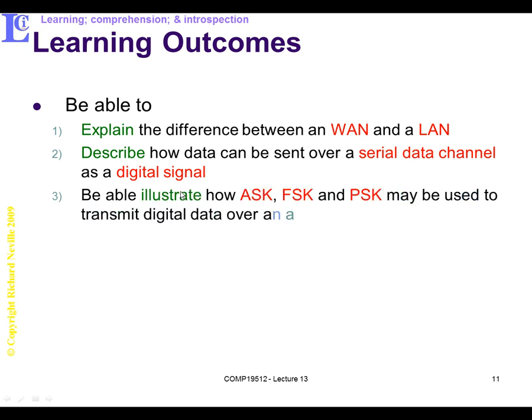Then we move on to talk about the fact that in reality we cannot send a digital signal across free space. That means wireless transmission and Wi-Fi is not digital. You might have thought it is. The main reason for this, a bit beyond the scope of the course, is that if you ever worked out how to transmit a digital signal, you should go down to the patent office and patent it, because it's nearly impossible. Think about how you transmit that transition from a 0 to 1, and how you'd make that change from low to high very quickly. It actually requires a very, very wide bandwidth, so it's not done. What is done is simple narrow bandwidth signals, which are called analog signals. So we're going to look at a number of methodologies for putting data onto analog signals.